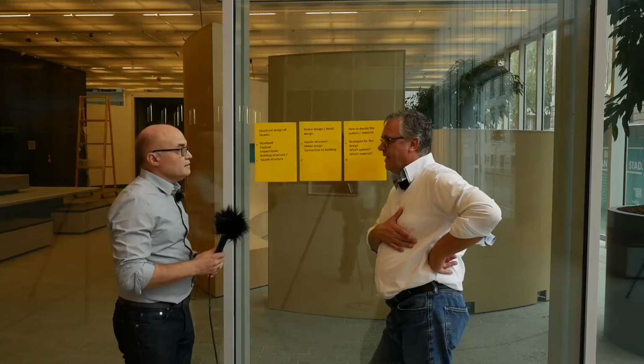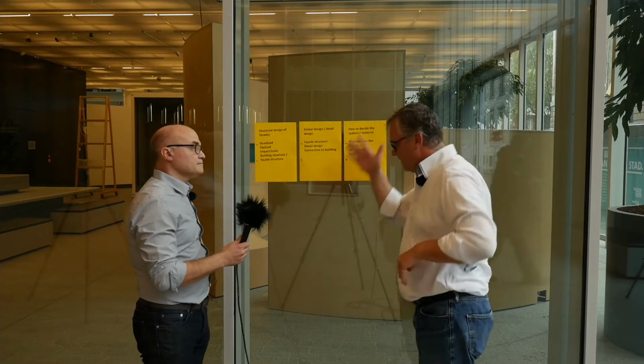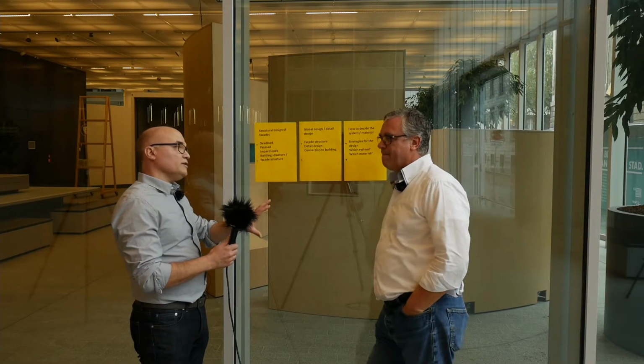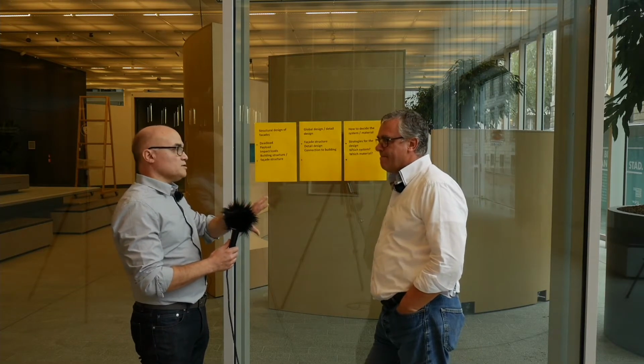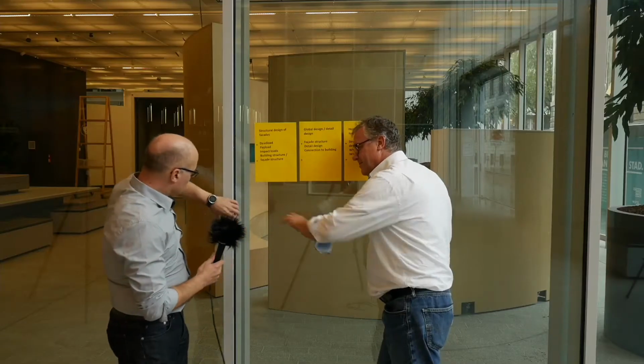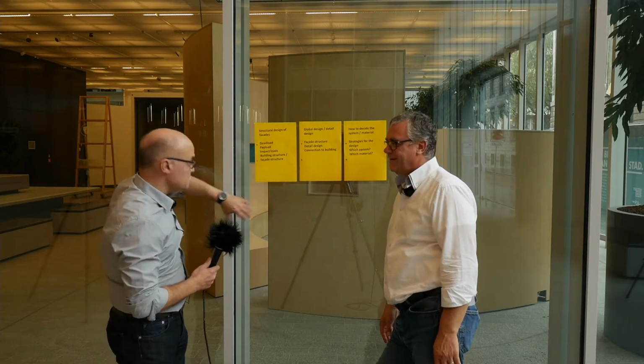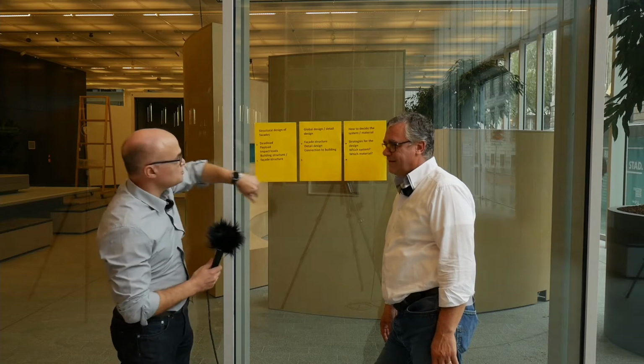And then these loads, as you said, they come from the panel, they get into the system, and then they get down to the building. How does that work? So the best way to look at it is from where the load is acting. If you have a wind load, the first thing the wind load acts on is the glass panel, in this case. So the glass panel must transfer that load safely to the facade frame system, whether horizontally or vertically, but in this case probably more horizontally because the span is shorter horizontally.